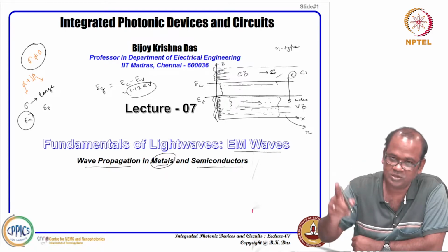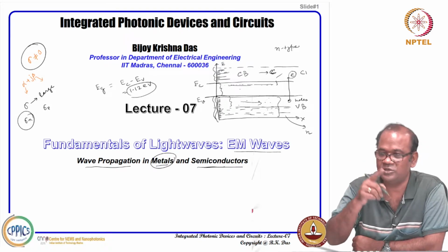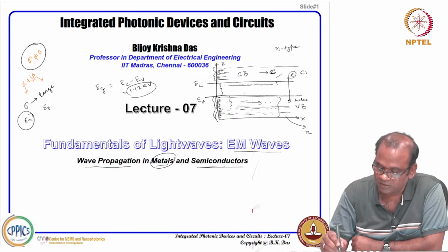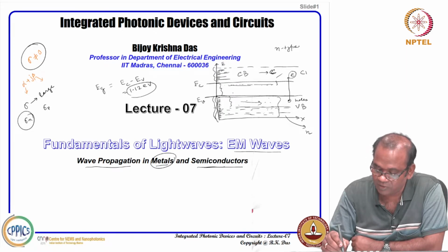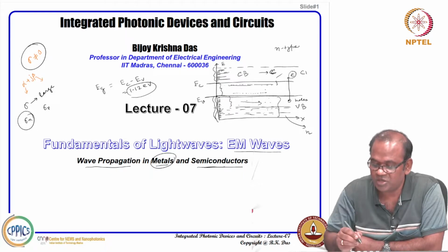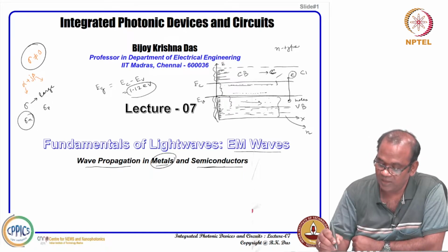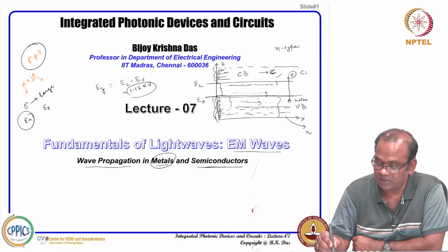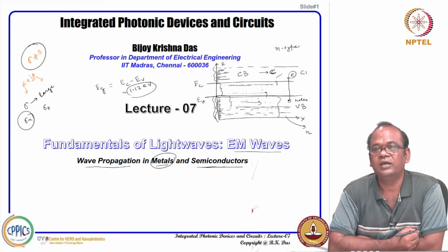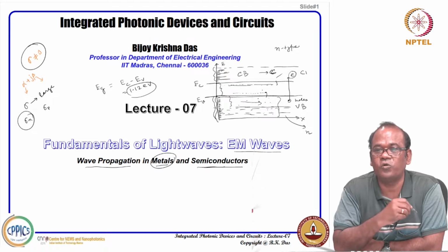Boron has 3 valence electrons, whereas silicon has 4. So, that fourth electron which is not available in boron will occupy a state somewhere just above the valence band. So, in that case some electrons can easily gain energy and occupy that state, and it will be attached to boron.